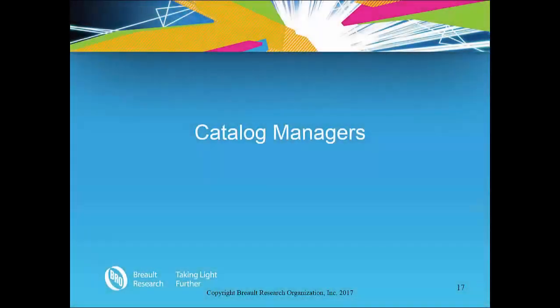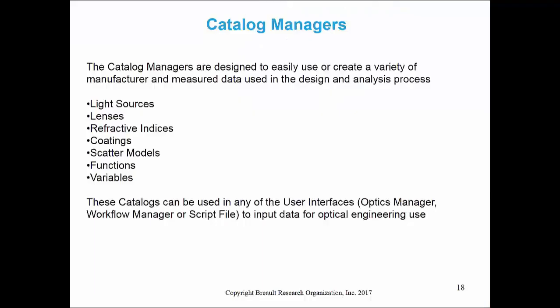Before we discuss the optics and workflow managers, let us spend a few minutes introducing catalog managers because they are used for both the optics and workflow managers and many times are the starting point for simulations. Catalog managers are software tools designed for you to manage a variety of data commonly required for optical simulations. This data can include a variety of manufacturer and measured data for light sources, lenses, media, coatings, scatter models, functions, and variables to input data in any of ASAP NextGen's optics, workflow, or script managers.